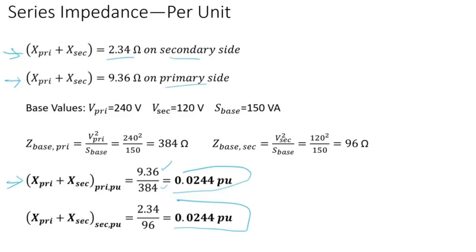For the short circuit test, you energize one side, and the other side you short circuit all the terminals. You take 3 terminals and put a wire across all of them so they are short circuited. So it's the same test, so I might do a quick video on that, but I wanted to start with single phase since it's easier to demonstrate and easier to understand.